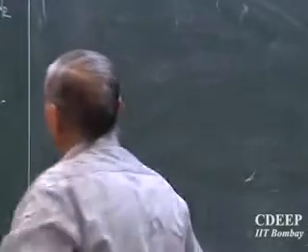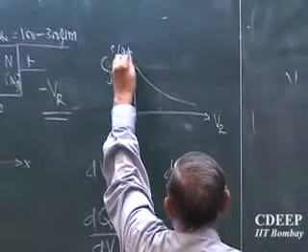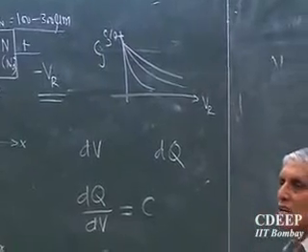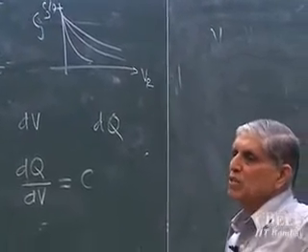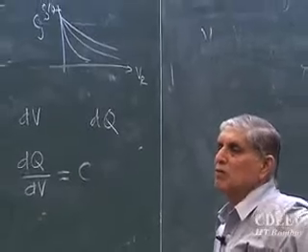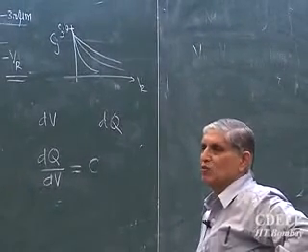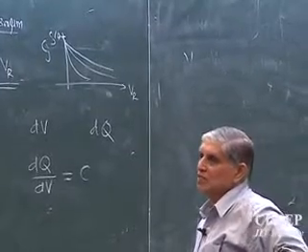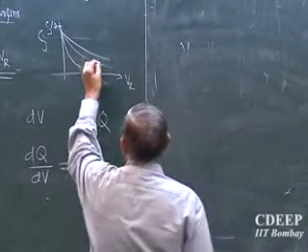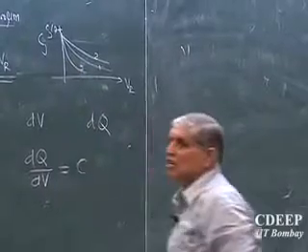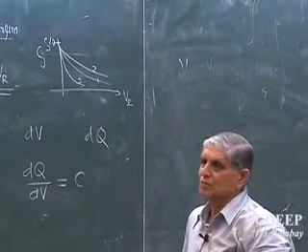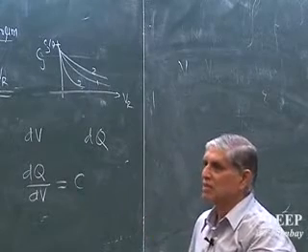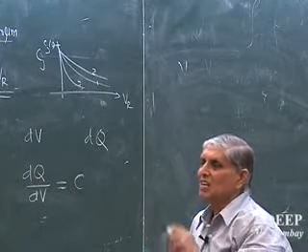There is a possibility that you can have this, or you can have this, depending on the dopings you use. Which one would you prefer for a tuner? For tuning purposes, I want the capacitance variation that gives me a larger range of tuning. Let's say these are curves 1, 2 and 3. Which curve will you prefer for a good tuner? Let's say my requirement is that I must cover a larger band. Which one? Curve 2. Is that clear to you?